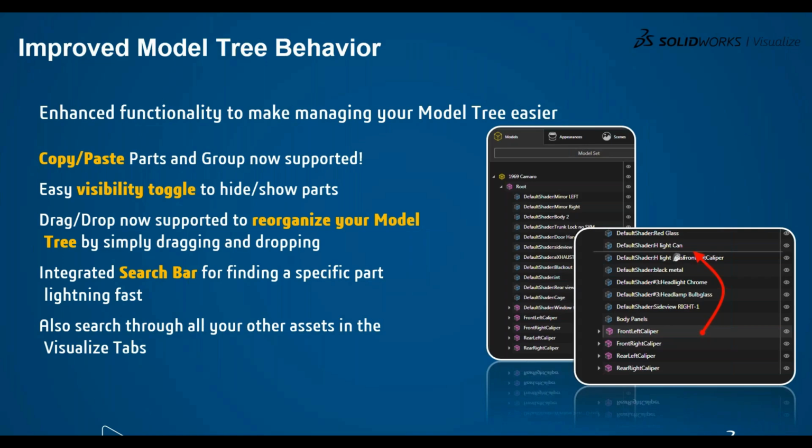Another importing style is exactly the tree structure followed in SolidWorks, and the same can be imported here. This will help you on the selection mode, like if you need to select by assembly, part, group, or appearance. Why? Because if you're selecting one object, it might be an appearance selection. You need to select only the appearance, or only the part, or only the group, or the entire assembly. So that selection mode will also be helpful in this tree behavior approach. And we have also incorporated a search bar, which will help you on searching for a component inside your huge assembly.